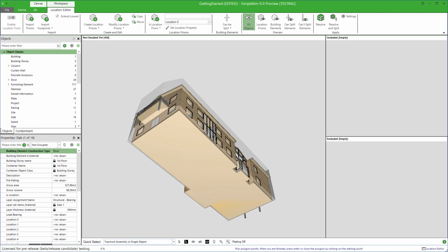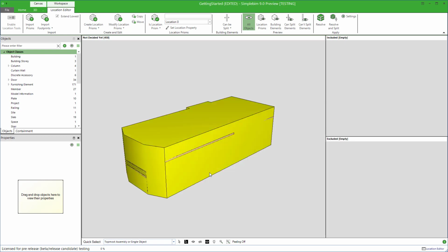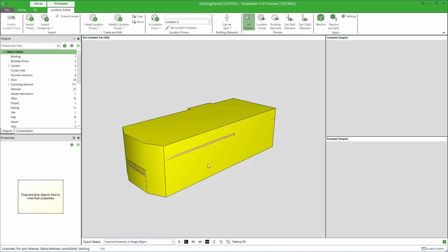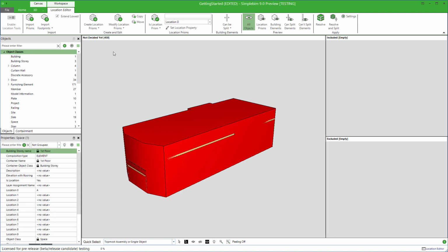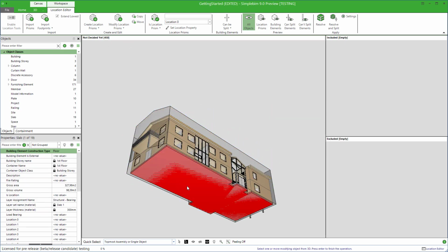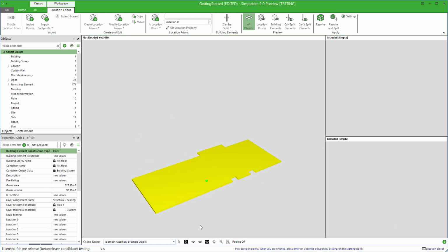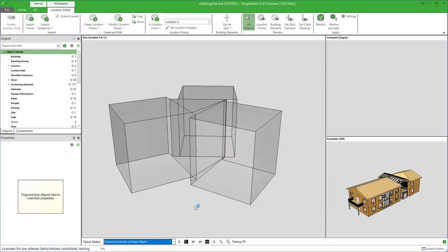The third modify option is the intersection. Again, you can intersect two or more prisms, or even prisms and building element geometries. Let's go back to the first prism we used. As you can see, it covers the slab. This time, instead of subtracting it, we want to create a location of its own for the slab. So select the prism, click Intersect from the menu, select the slab, hit Enter. And now you have a prism which exactly covers the slab. Nice.